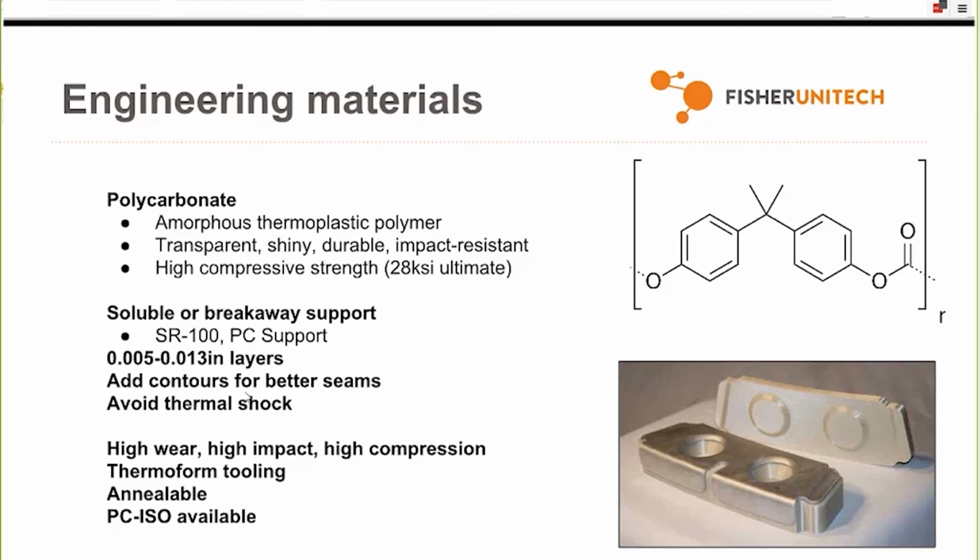I've also personally found that polycarbonate tends to under-extrude whenever it starts the build, the contours, perimeter contours. And so I find that it's worth the time to open the file in Insight and add an extra contour. And I always check the box to link contours. And I find that helps to improve the appearance of those seams.